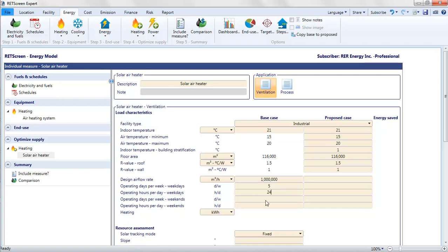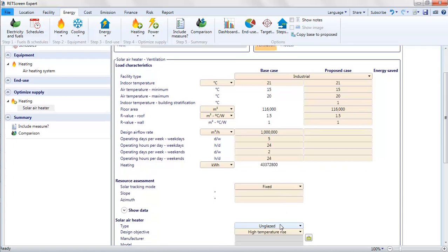We have a southeast and a southwest facing vertical wall where we can install the solar collectors. The slope will therefore be 90 degrees. For the azimuth, RETScreen does not differentiate between east and west, so southeast and southwest are both 45 degrees. I can consider this to be a single wall with an azimuth of 45 degrees, therefore.